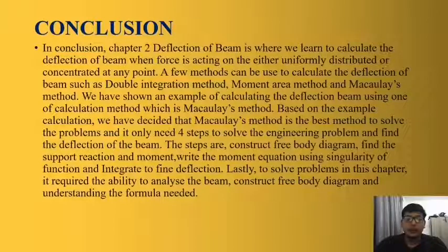The steps are: construct free body diagram, find the support reaction and moment, write the moment equation using singularity function, and integrate to find deflection. Lastly, to solve problems in this chapter, it requires the ability to analyze the beam, construct free body diagram, and understand the formula needed.